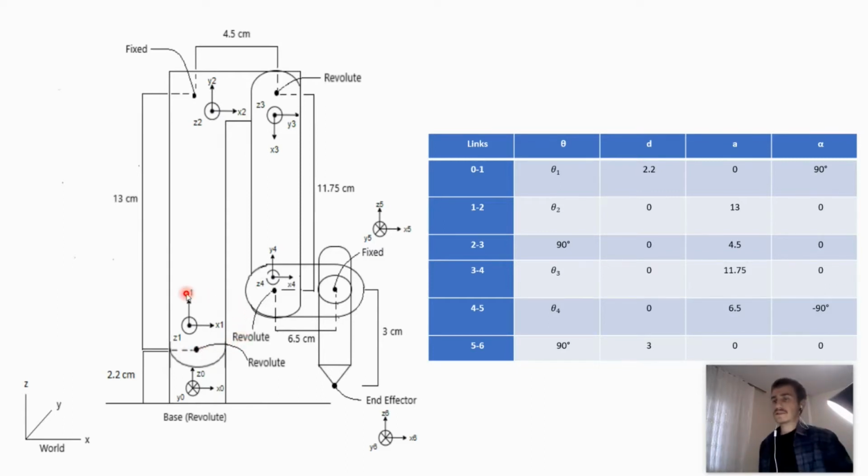And using these illustrations, the DH parameters of the robotic manipulator can be obtained. The DH parameters are necessary because in the 3D simulation environment, they are used to create the 3D rigid model of the robotic manipulator.